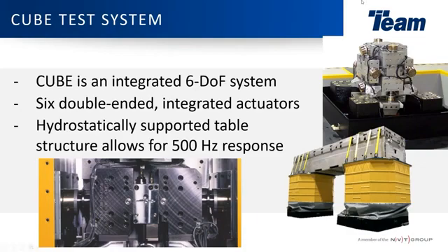This has an integrated voice coil servo valve down in the center section of the actuator. So in the bottom left, you see a closer picture of that cube actuator, or one of them. So there's 6 of these. And this is actually a dual stage pilot and slave valve with up to 140 liters per minute. So you could still achieve about 40 to 50 inches per second on a cube, all while in quite a compact space.